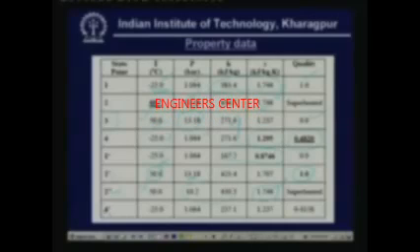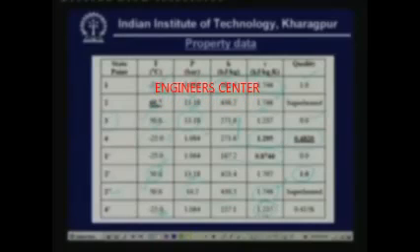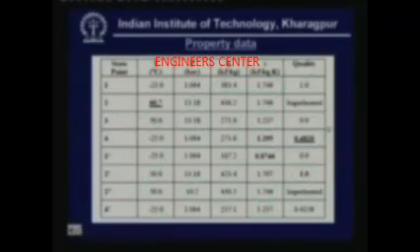Finally, point 4 dash, at point 4 dash we know that the temperature is minus 25, and we know that at this point the entropy is same as that of point 3. Okay, so, this is same as 1.37. So, we know the two properties, so we can find out the rest of the properties. So, this is how we found the properties at all the points.